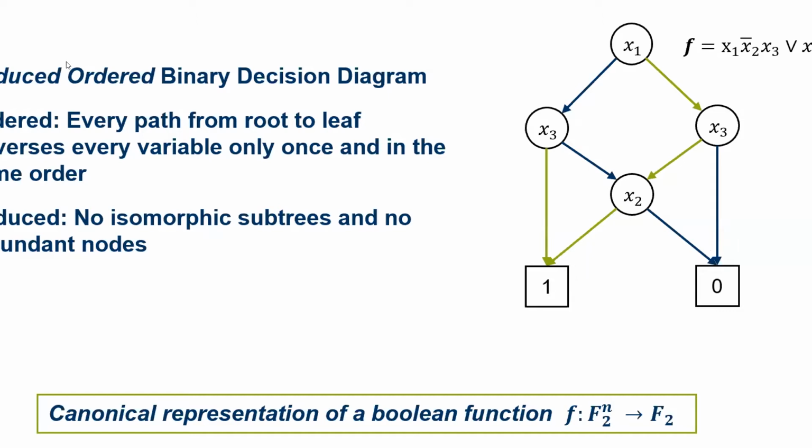What is quite handy is that using ROBDDs to determine the distribution at the output is a well-examined topic. So we determine the probability. Basically, if we say the input variables are independently and identically distributed, it's a counting problem. We count for how many inputs the function is 1 and for how many inputs the function is 0, and this can be done efficiently with this structure.